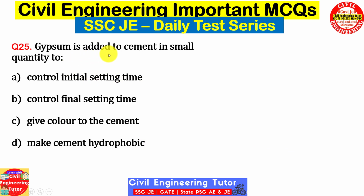Next question: gypsum is added to cement in small quantity to control initial setting time, control final setting time, give color to the cement, or make cement hydrophobic. Now we can eliminate the option that gives color to the cement. This is not the purpose of adding gypsum, and we can hardly temper the final setting time. It is very difficult to temper final setting time, and the correct answer for this case will be control initial setting time.